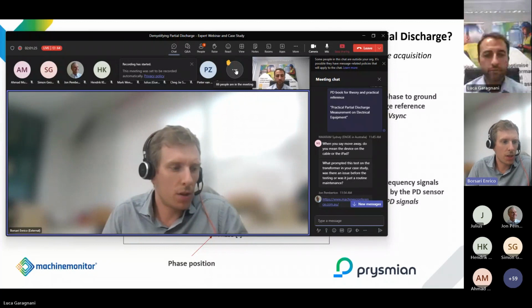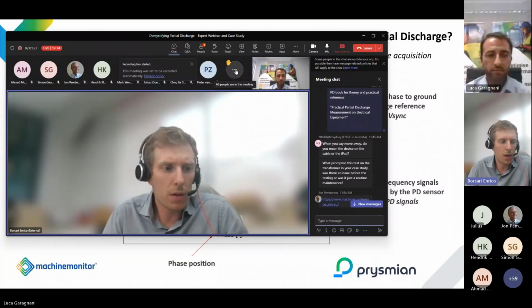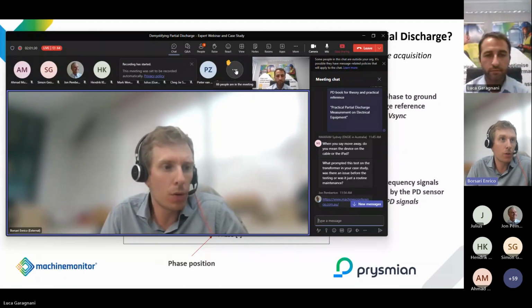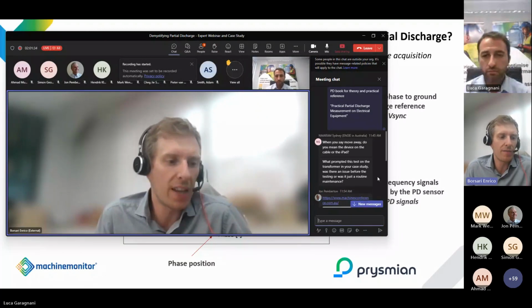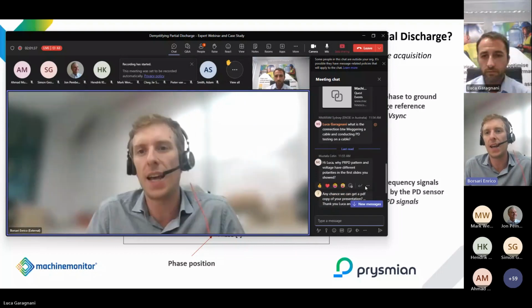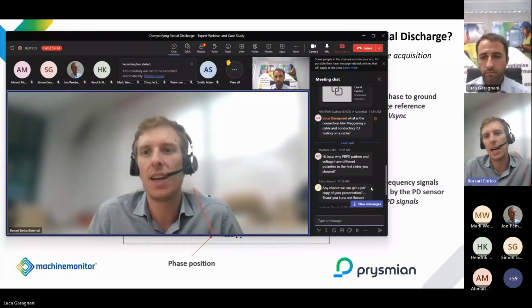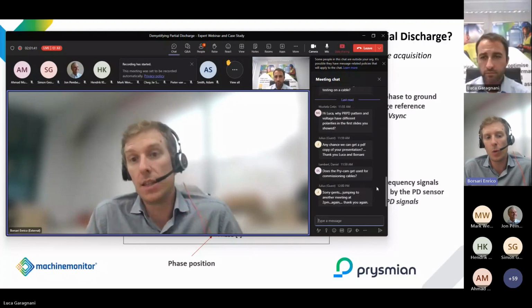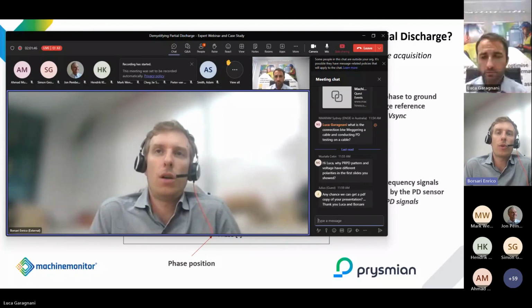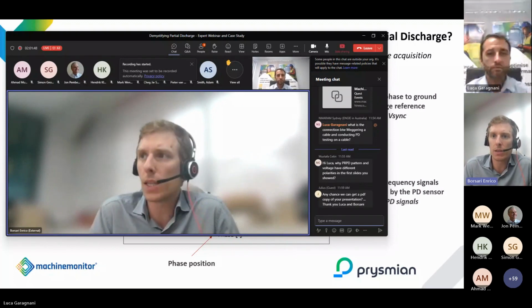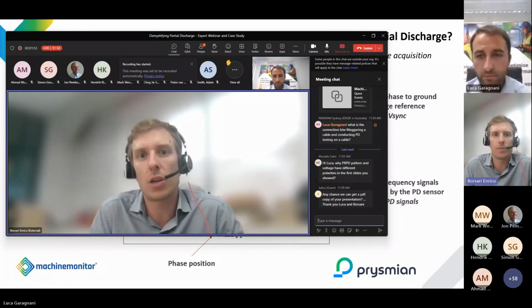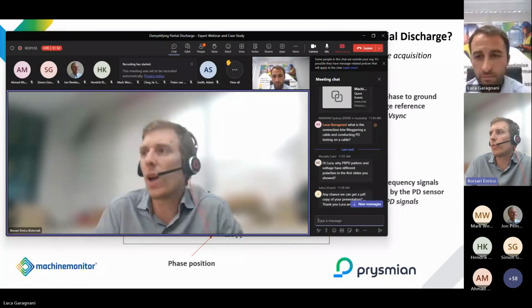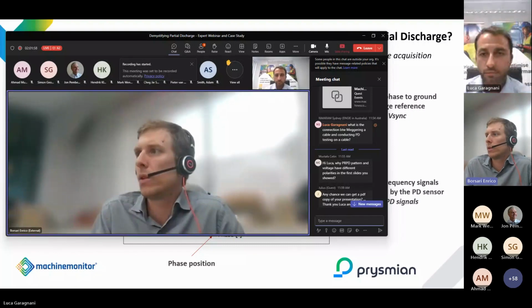Yeah, there was a history of failures, and the customer wanted to make an assessment on whether preventive maintenance tools and habits could prevent these faults. By showing that we were able to detect a partial discharge, we were able to demonstrate that yes, preventive maintenance is the way forward, at least for this type of discharges. Lead the way before they become fault.